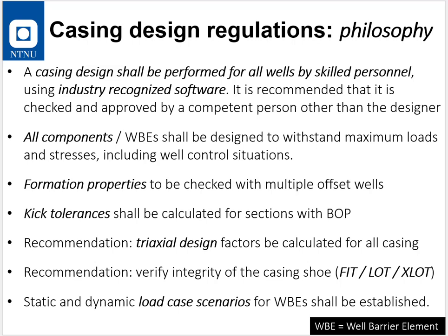Software is software, and you have to understand the people who made it and that the result of the software is okay. All components need to withstand the maximum loads and stresses through the life cycle of the well. You need to have a full understanding of the formation properties, and you need to be able to calculate the kick tolerance. And that's for all sections that you have a BOP installed.